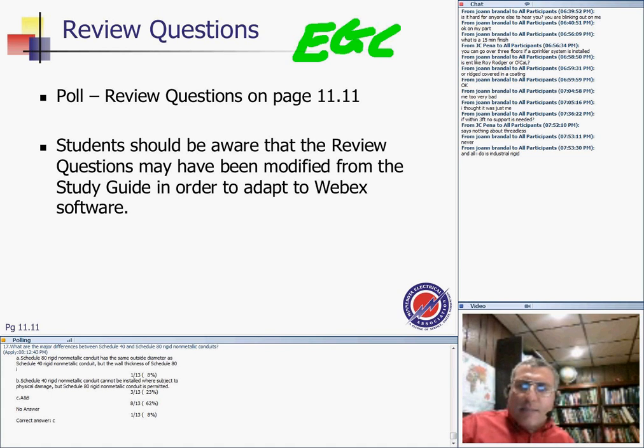Questions, guys? Any comments about the EMT? EMT is your conduit of choice when it comes to commercial buildings and a lot of indoor dry or damp locations, guys, especially dry locations. It's going to be your conduit of choice. And easy to bend, as you can use the hand benders as we covered a long time ago. It seems like last year at least.